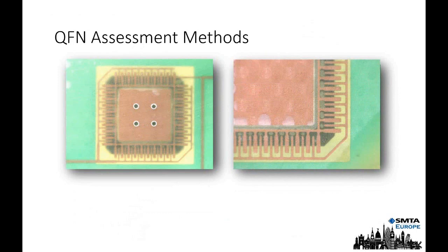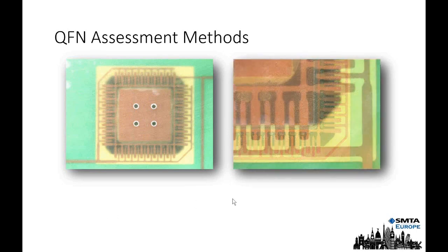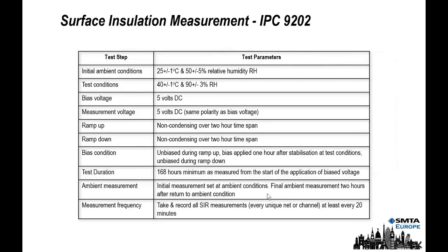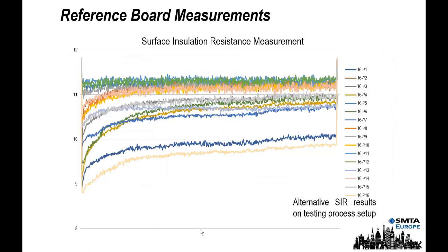Of course, you can use X-ray. An X-ray will pick up dendrites, I pretty much guarantee it. You have to take a little bit of time to find them, possibly, but if you look at the data, that will indicate where they actually are on the board. But a close-up view like this through the board with backlighting is surprisingly good at showing where corrosion has taken place. So basically, setup and criteria of your traditional SIR is highlighted here, and this is obviously documented in the IPC standard.